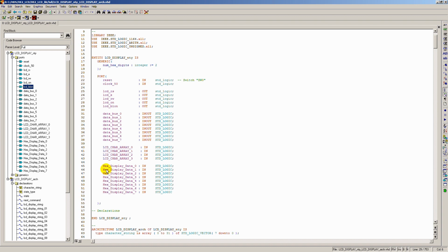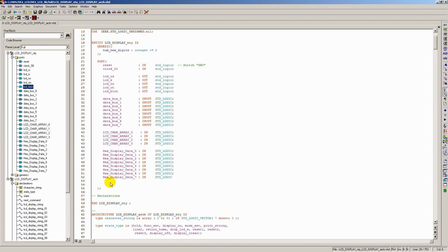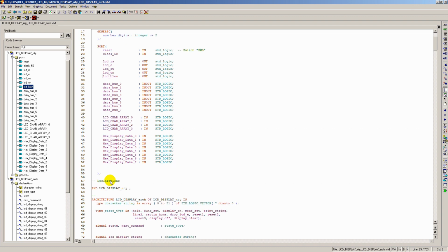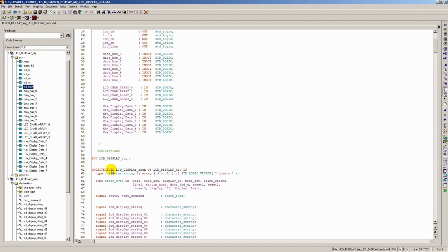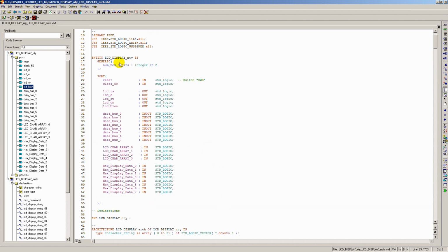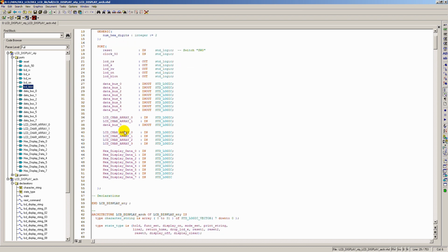It's a way of displaying 2 characters showing a hexadecimal value on your display in real time, as it monitors these particular pins that are hooked up to logic switches on your development board, or part of your design that you have incorporated with your FPGA. So that's what the entity section does. It's just mapping all of our input ports and output ports.